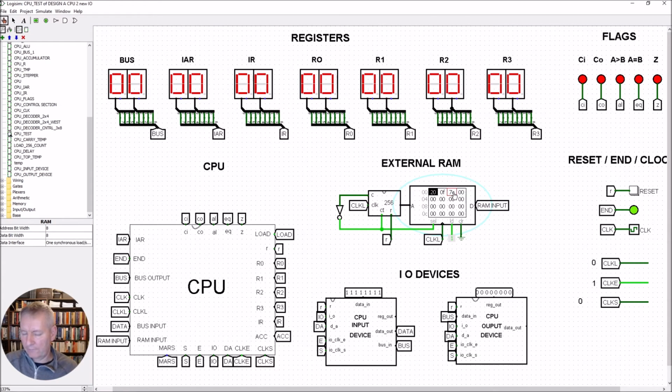So the other part of it just tells us, the other 4 bits tells us whether it's an input, output, data or address, and then the last 2 bits tell us what register we're going to or coming from. So that there just sets up the, puts the 0F onto the bus, and it registers the device. So in this case it's going to register the input device.